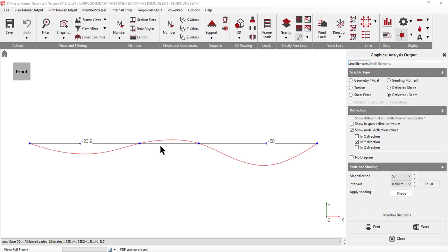If you wanted to do a beam with a spring support underneath it, you would need to introduce a series of little supports at every meter with the spring stiffness, and then analyze it as a super beam. Or you could try and do it as a finite element. Either way would do it.